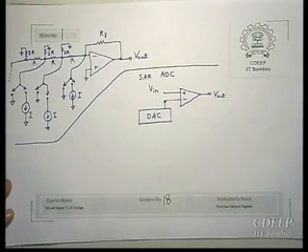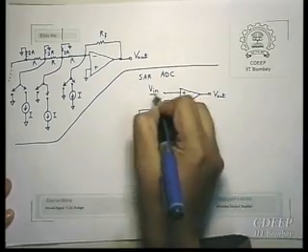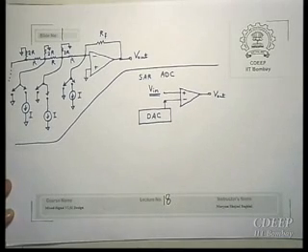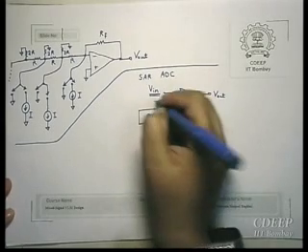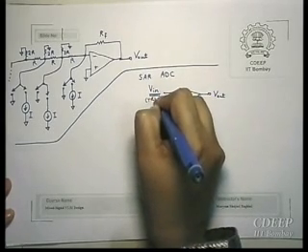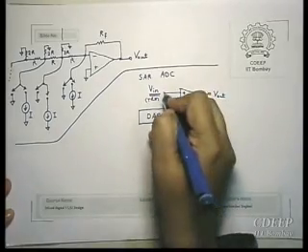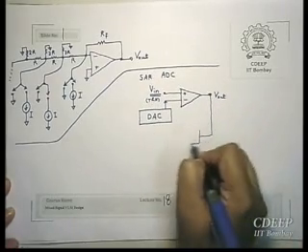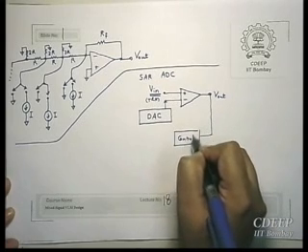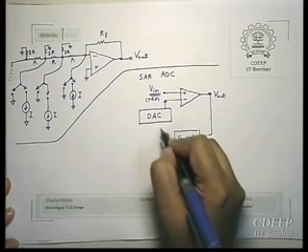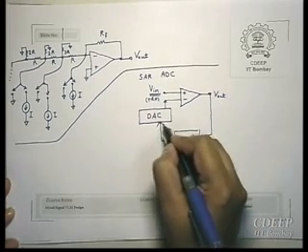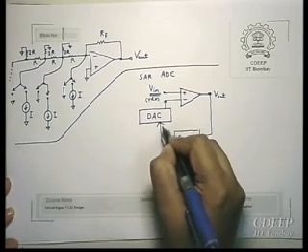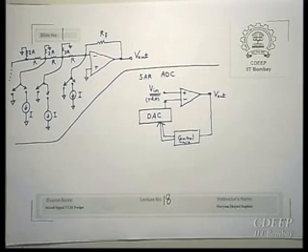Now we need to see how we can have this Vin. First of all, this Vin cannot be the analog Vin. Therefore, you need to have a sample and hold, or in fact track and hold, version of Vin at the input of the comparator. So this Vin should be track and hold. This is one thing, and the remaining part is the same as before. So here you will have the control you need, and this is now your parallel charge scaling DAC, which will have enough control lines.